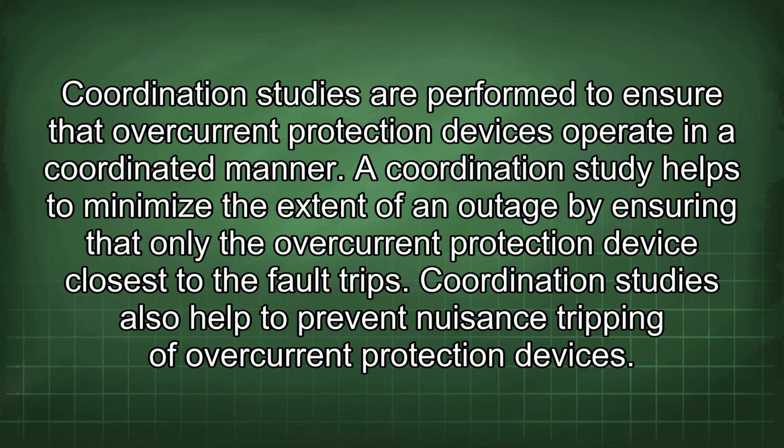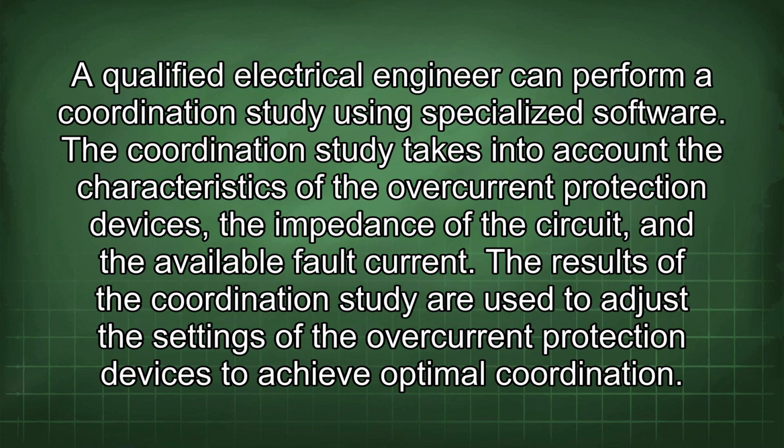Coordination studies are performed to ensure that overcurrent protection devices operate in a coordinated manner. A coordination study helps to minimize the extent of an outage by ensuring that only the overcurrent protection device closest to the fault trips. Coordination studies also help to prevent nuisance tripping of overcurrent protection devices. A qualified electrical engineer can perform a coordination study using specialized software. The coordination study takes into account the characteristics of the overcurrent protection devices, the impedance of the circuit, and the available fault current. The results of the coordination study are used to adjust the settings of the overcurrent protection devices